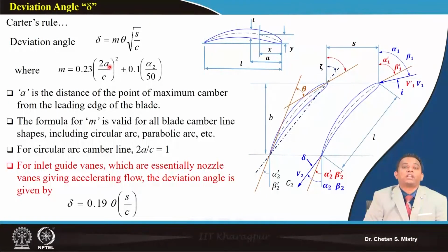We also started discussing that with the change of incidence angle, the deviation angle at the exit changes. We learned that deviation angle is prone to happen because of the inherent property of our aerofoil, and we need to be very careful in calculating it.